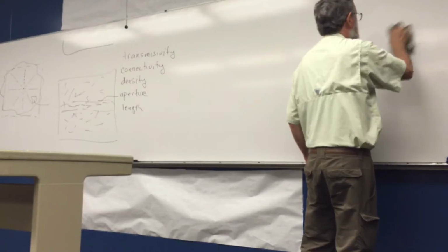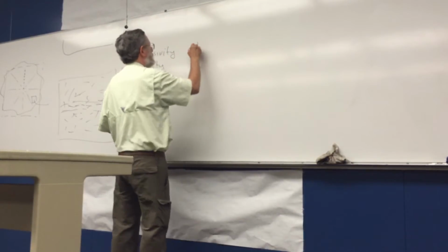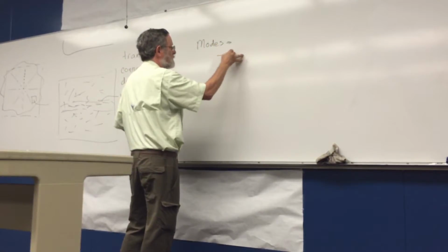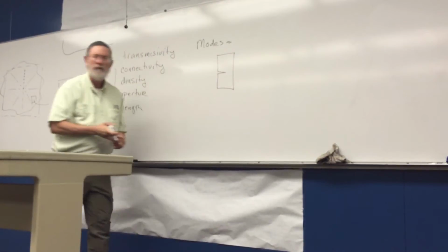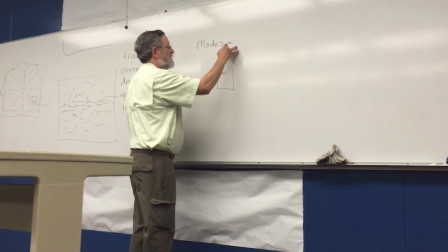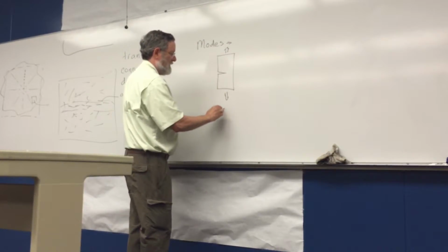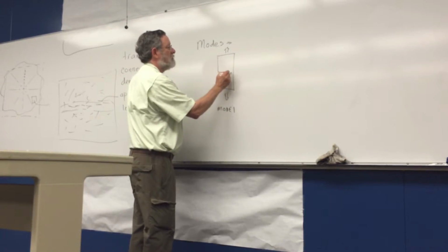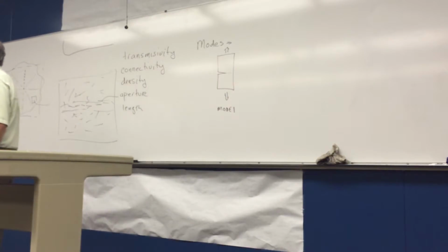We talked a little bit about the modes of fracture, and we kept fairly simple fracture modes where we imagined a flaw here. This flaw, if we try to propagate it doing pure tension, this would be a mode 1 flaw, and it would tend to propagate as a straight plane.